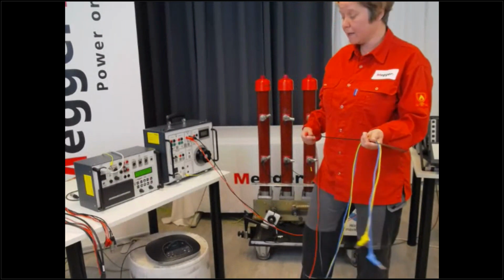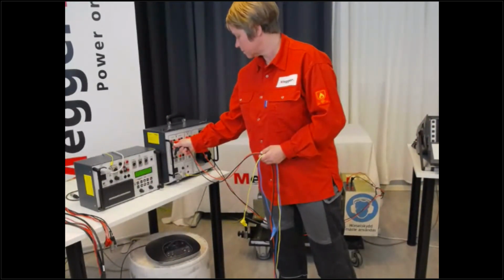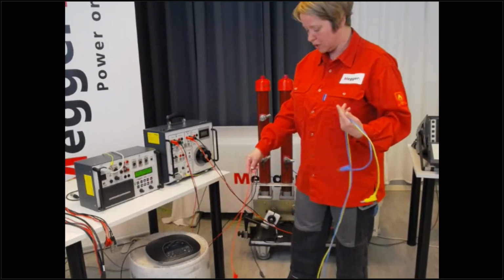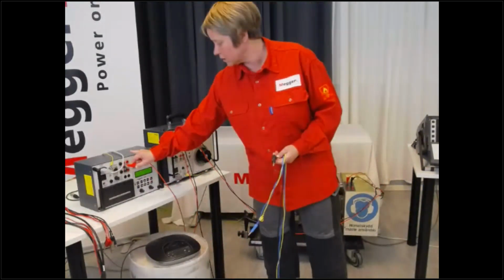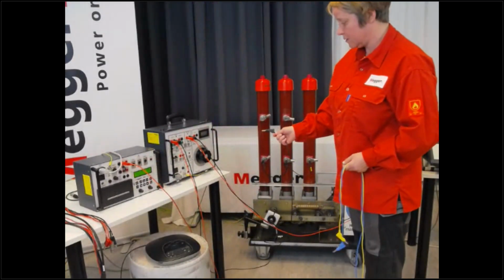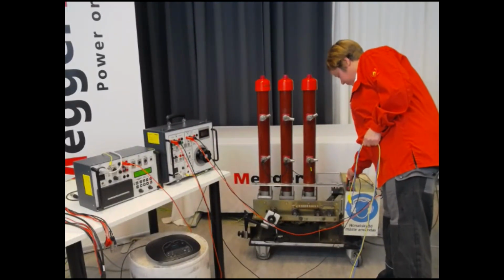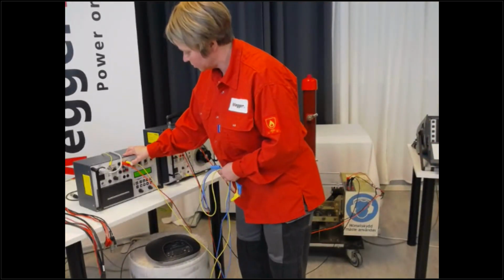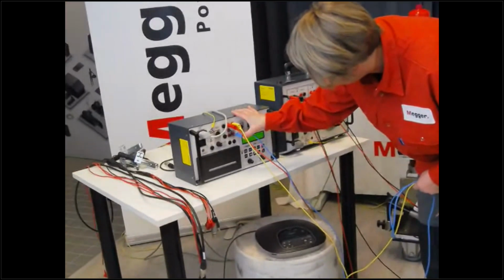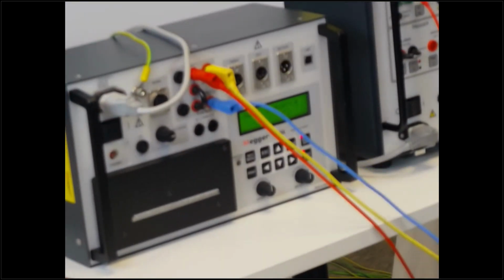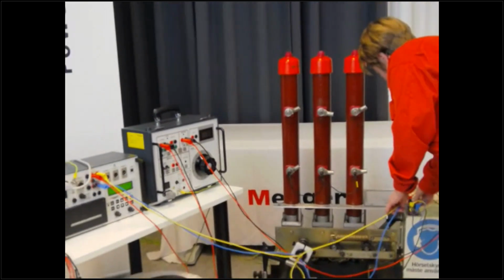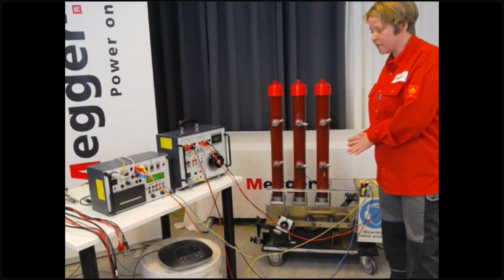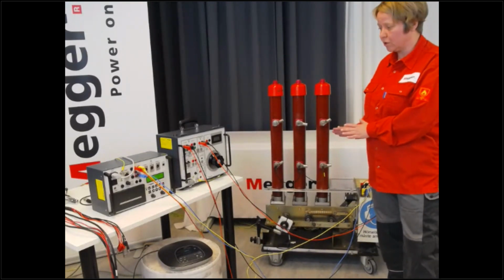I need the supply for the coils, the plus and the minus. And what I'm going to do here, I'm going to use the plus to create the pulse. So the plus goes to the analyzer and it will meet the minus on the circuit breaker, on the coil for the circuit breaker. I also need to connect the close and the open. The close on the instrument and the open on the instrument, and close and open on the object. There's no reason to show you any details on the connection on this side because this will be special on any circuit breaker and you will not have the same object.